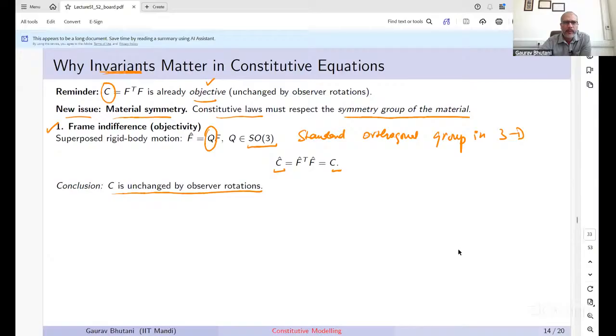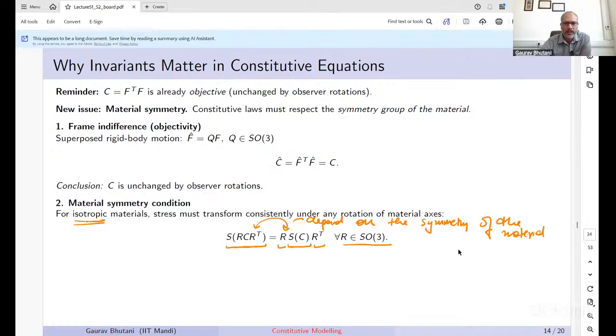Then we very briefly talked about the ideas of invariance and constitutive equations. You will notice that in the typical form of the constitutive model, the invariants appear as coefficients rather than some terms of the Cauchy-Green tensor, that is C. So the C tensor would appear in the model from the representation theorem, but the terms of C will not appear. The coefficients will include the invariants of C, as we typically see in isotropic tensors.